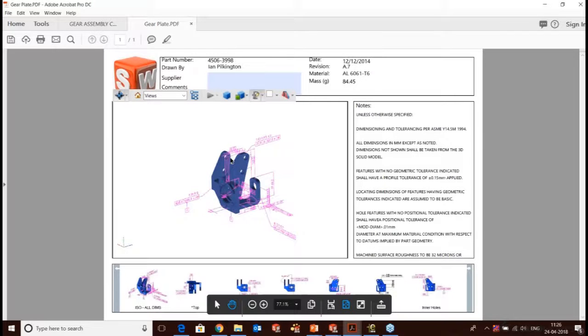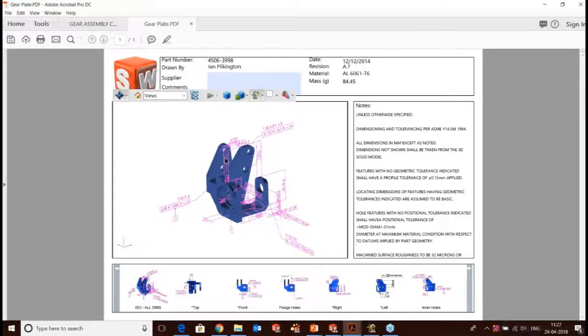And normally what happens in 2D drawings is the person looking into 2D drawings might get confused if there are many dimensions. Basically, if there are many linear dimensions that have been given, he'll not know from where it is starting and where it has to end. So these kinds of confusions will be there. But inside SolidWorks, there is an option where we can cross highlight. So whenever I select a dimension or a feature, it will cross highlight from which plane to which plane the dimension is applicable. So this will reduce the burden on the person who is reading the design or reading the drawings.